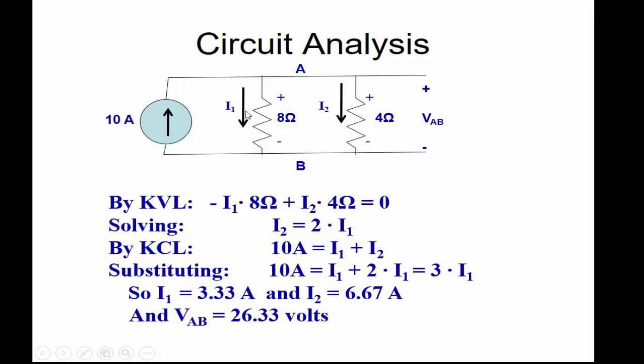These two resistors are in parallel, so we can find the equivalent resistance, which is the one we have in parallel with this. This is an open circuit, which means the equivalent resistance times the current in amps will give us VAB.